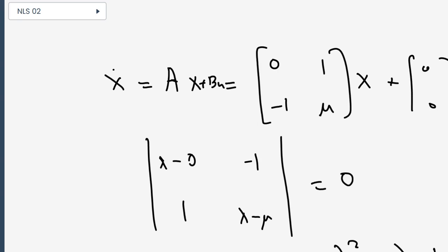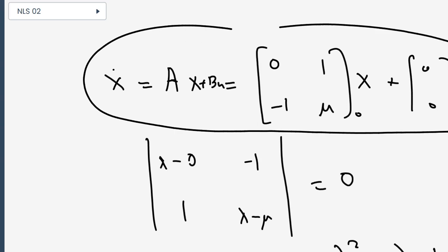So this is the A matrix. Then after substituting the values of x1 and x2 obtained at the operating point, substitute them here as well as here. This is now your linearized state space model of the system. Once you have the linearized state space model, you can find out whether the system is controllable, whether it is observable, what the states are, and whether the system is stable or not. So all that analysis you can do in the linear domain once you have the linearized model.